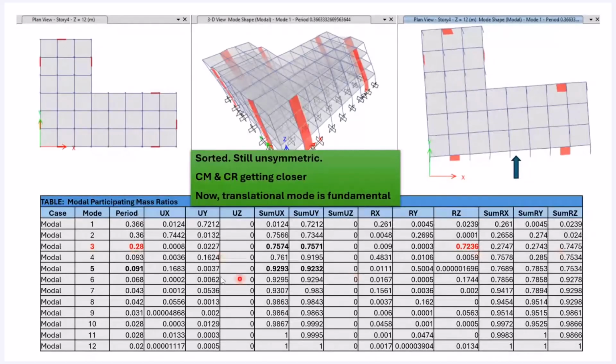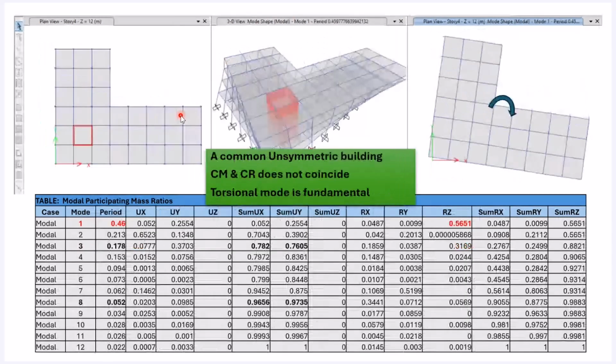The other thing is the separation you can also see between the torsional mode and the translational mode, right? So the thumb rule is that the primary structural modes should stay away from each other by significantly, as much as 10% at least in an ideal situation. But here we are achieving that with this distribution, right? Here it is dominant, has to be avoided.